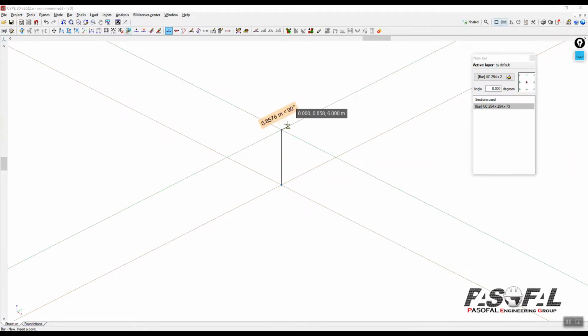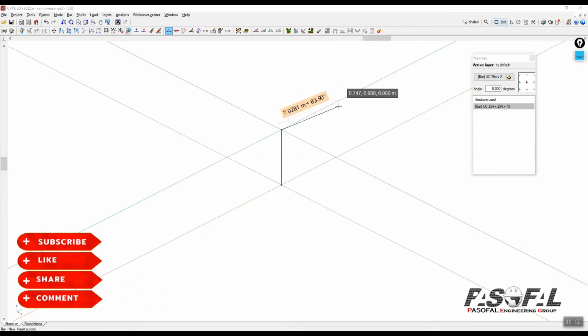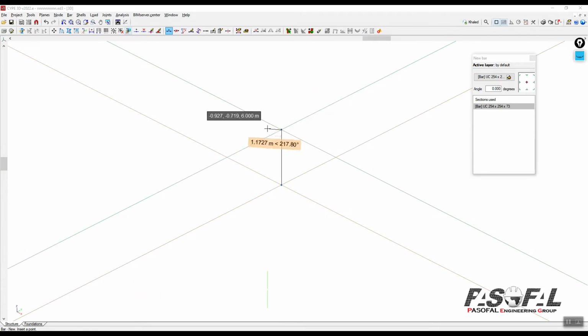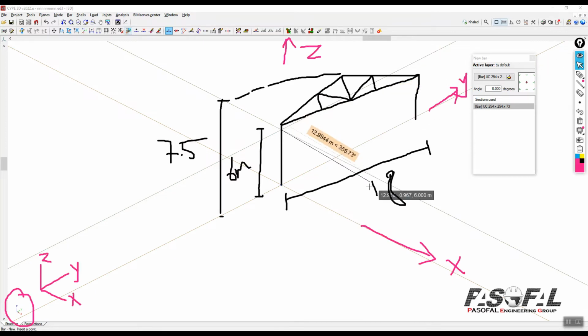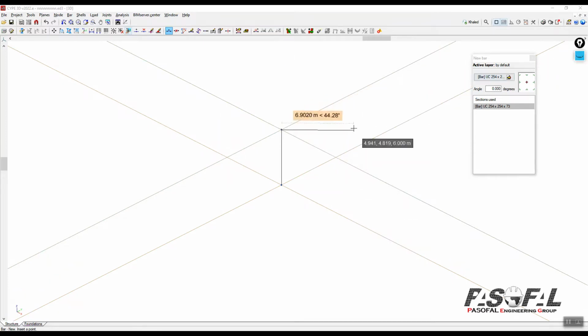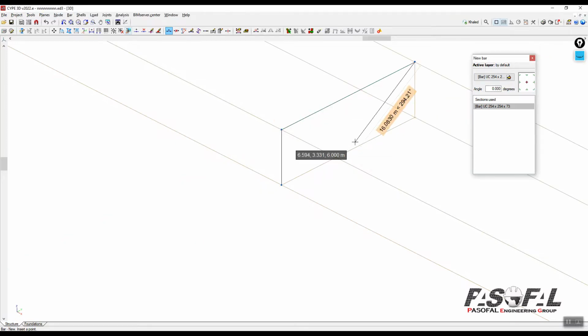As long as you have this, another reference line corresponding to this node will be created or generated, in Y direction and also in X direction, and then you can use this reference line to complete your model. For example, in this direction, if you remember, we said that we have 18, and that's why simply I can go this way. Again, it doesn't matter. For example, here I'm going 4.4 meter. I just need to click here and write 18 and then press enter.